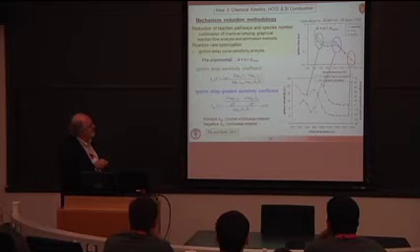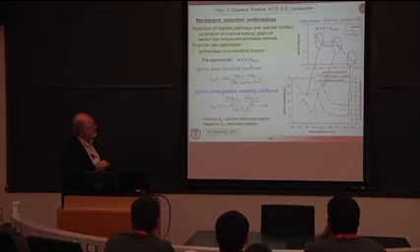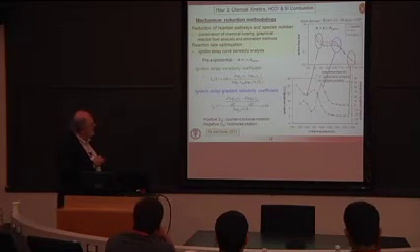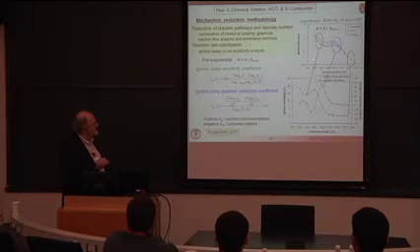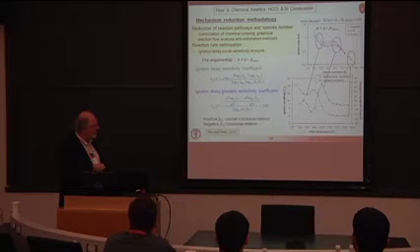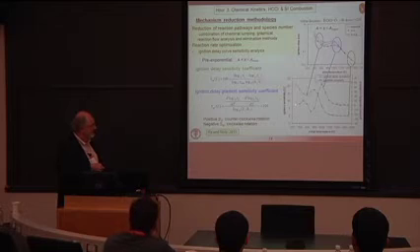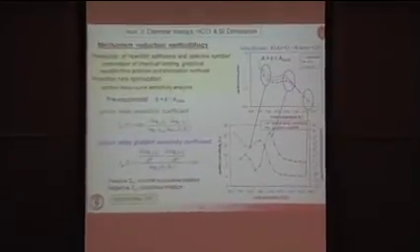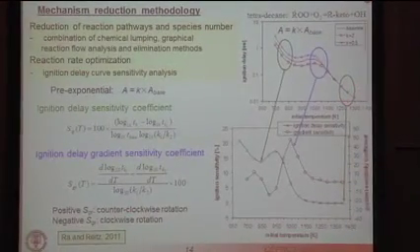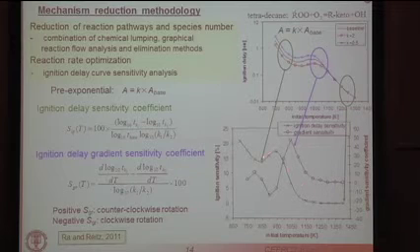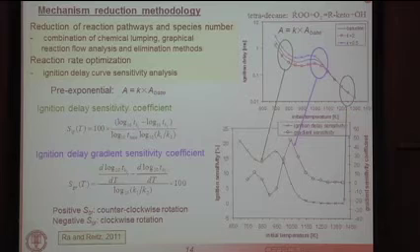Well, here he's looking at just one reaction, peroxide going to the keto species for a tetradecane mechanism. So he identified what he calls ignition delay sensitivity coefficient. Essentially look at how much the delay time changes here as a function of temperature. You can plot that on this plot here as your ignition delay sensitivity versus temperature. And what you find, as you can see with your eye, is that it's high in this region, but at high temperatures, that particular reaction doesn't play much of a role. Well, we already saw that, right? These keto reactions are low temperature reactions. But anyway, this plot here allows you to identify the temperature range over which that particular type of reaction would be important.